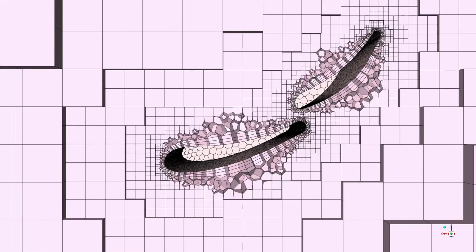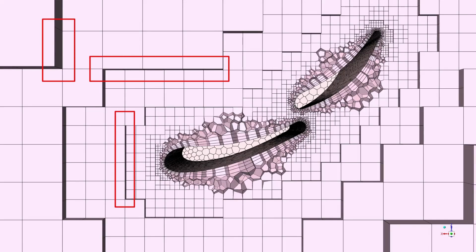Based on originally estimated mean and max size of 2 mm and 128 mm, considering the octree meshing scheme, there are 7 distinct layers of hexahedral elements with different cell sizes. At the transition location between levels, the larger cell is split into 8 smaller cells, which is generally referred to as the 1/8 octree transition. This leads to the creation of hanging nodes for the finer cell size layer.